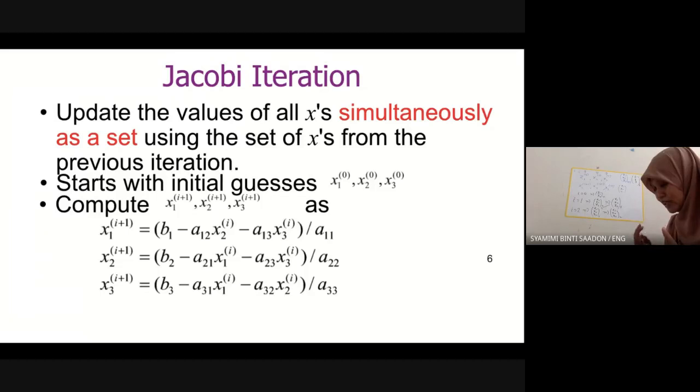A higher value of the number of iterations I is better, but again it will take longer time to solve. Sometimes the software will crash or jam, etc. So you need to use an appropriate, suitable number of I. For example, I usually start with I equals to 10, which means we do 10 rounds, and then we increase bit by bit, not too big.